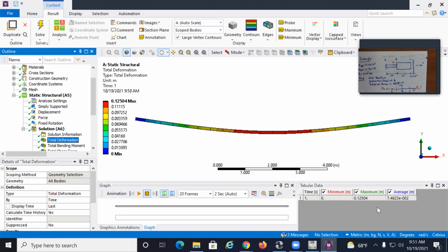Now, I would also like to mention that the stress sigma x could be a result of an Mz or an My, if I have double bending, or both combined. So I can come here and add to this plus My over Iy times, in this case here, z.